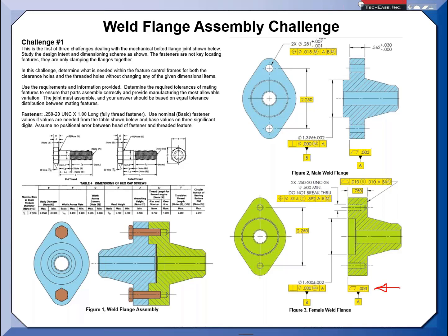would have to qualify in free state, but if it's a non-rigid part, what you might see is two feature control frames here, two different flatnesses. So in this case here, I might have another flatness here, and over here, let's say it's a very loose tolerance. So I put down, I'm gonna exaggerate. Let's say I make it 1/4 of an inch, 250. And you see this modifier over here, what we call a circle F, and I apologize, circle F. That's what we call the free state modifier.